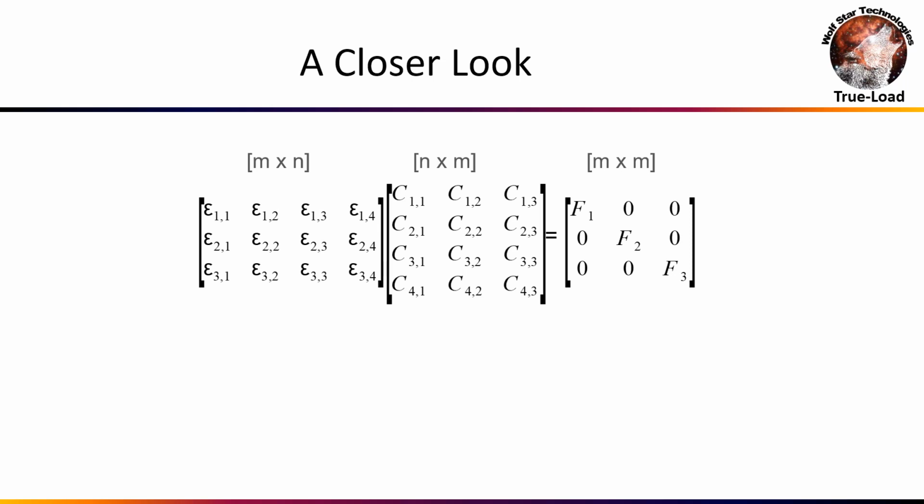Let me talk about these unit load cases for a minute. They could be loads, moments, unit displacements, pressures, thermal loads, inertial loads, they could even be mode shapes. If you set up gauges based on mode shapes, Truly will directly calculate modal participation factors just from the strain gauges. It's an extremely powerful way to understand the dynamic loading of your structures.